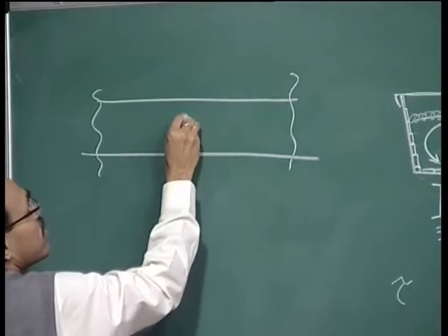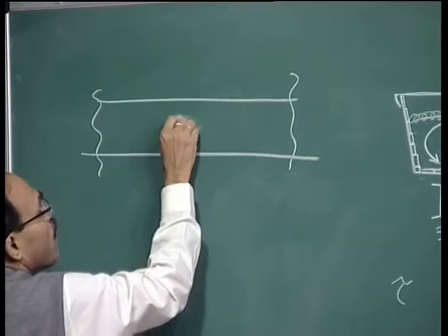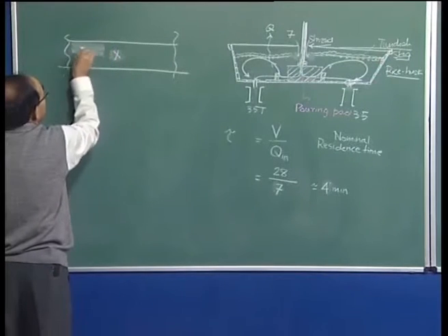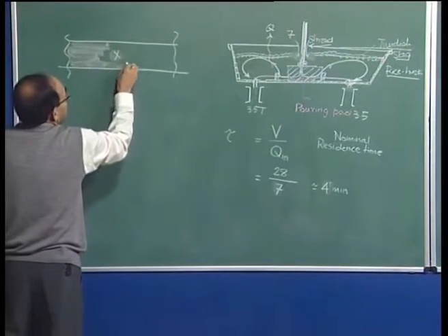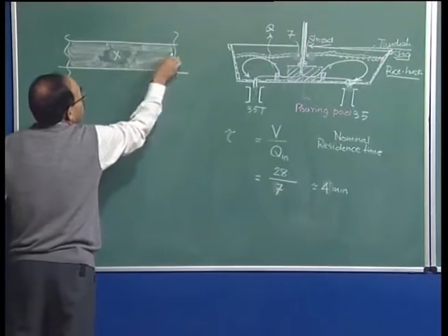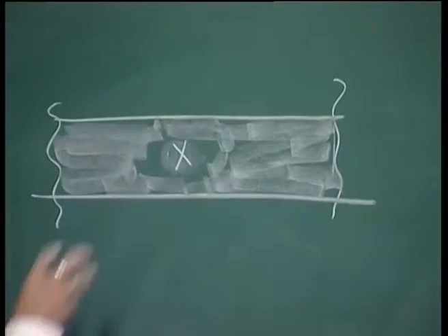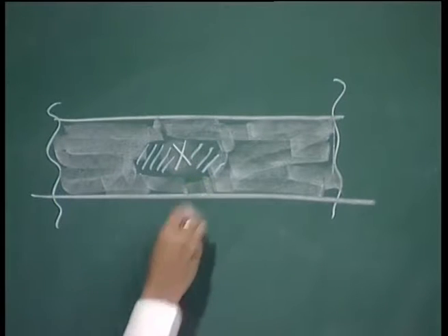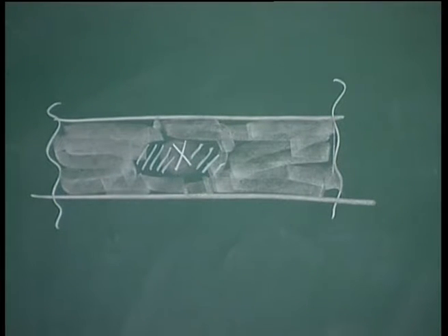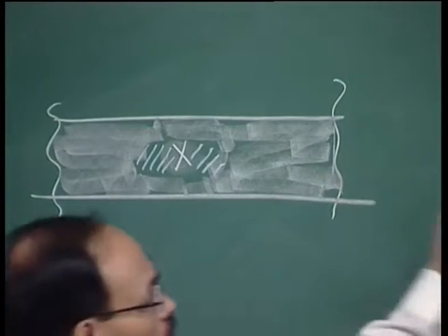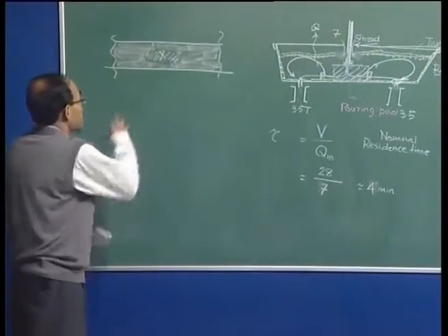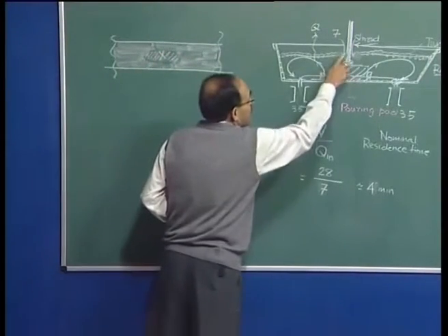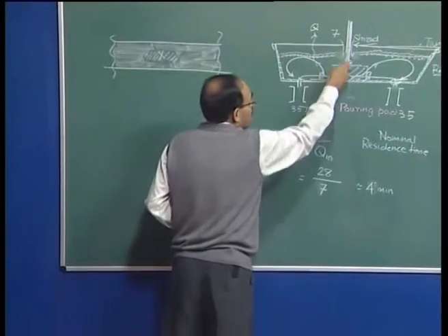So, this is the shroud region, and everywhere we have slag. Basically, that is what I am talking about: this region is going to be exposed. There is no slag here, and because of the high flow rate of molten steel, with no way to damp the turbulence itself, there may be a lot of activity. The slag droplets may be entrained here, and if there are no dams, etc., they may be entrained also.